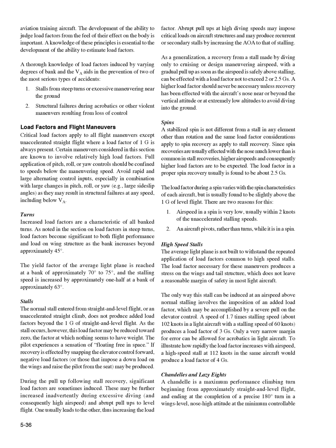The load factor during a spin varies with the spin characteristics of each aircraft, but is usually found to be slightly above the 1 G of level flight. There are two reasons for this. 1. Airspeed in a spin is very low, usually within 2 knots of the unaccelerated stalling speeds. 2. An aircraft pivots, rather than turns, while it is in a spin.